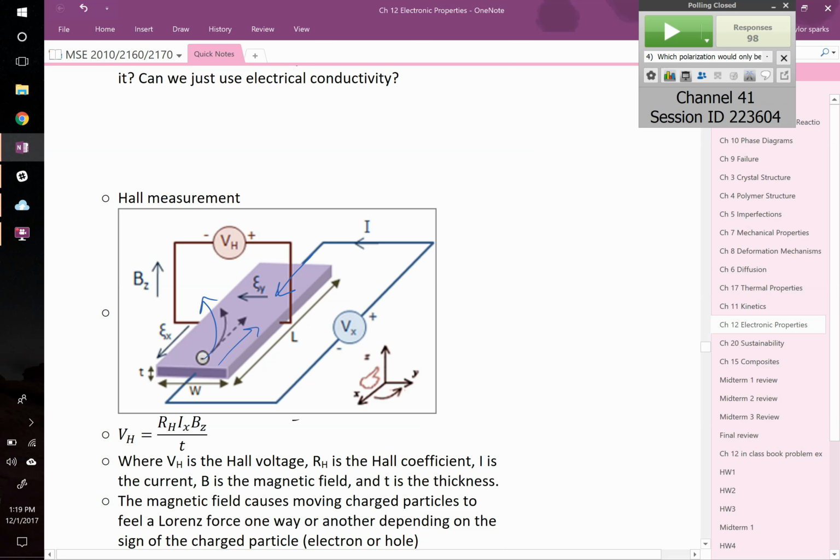So therefore, if your electrons are moving that way, you're going to actually build up a second voltage, one that you didn't actually intend for. It's called the Hall voltage, meaning if you measure the voltage from side to side of the sample, there will be a small but measurable voltage there. And from that, you can figure out the number of carriers that must be moving through your material, right? Once you know the number of carriers, great, you know conductivity and all sorts of stuff, right?